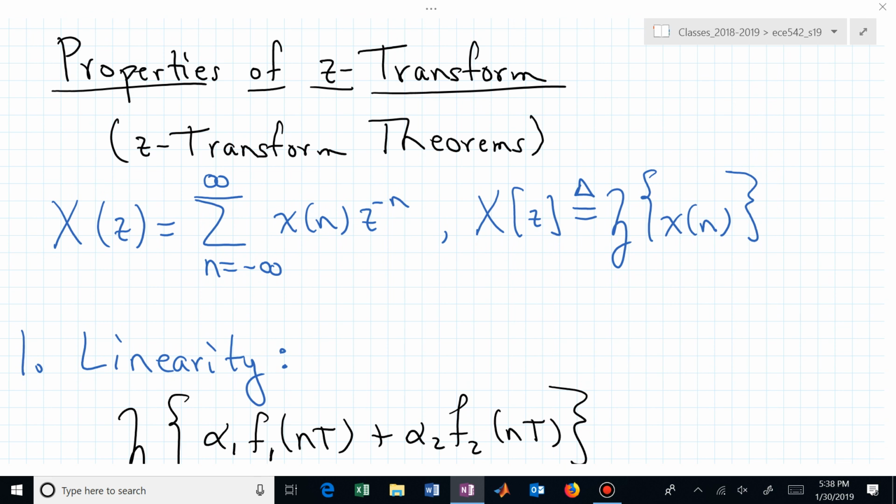Let's then move into the first topic, which is just a few of the Z-transform properties, and I've given you a chapter from a Schaum's outline, in the course resources section. It's a chapter on Z-transforms. It's also in the material that I've provided for notes on discrete time system foundations. And today we will just say, here's the definition, and we may use this script Z with the argument of that script Z being the time domain waveform x of n. And if we Z-transform that time domain waveform, little x of n, that gives us capital X of z. That's the notation where capital X of z is this infinite sum weighted by these z to the minus 1 weights, z to the minus 1 raised to various powers.